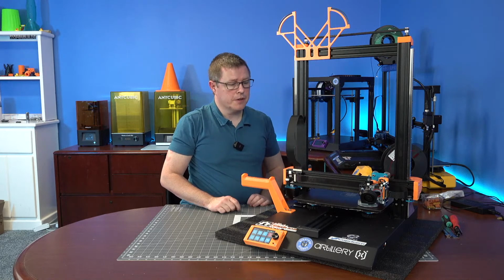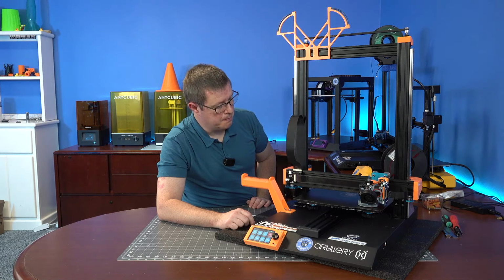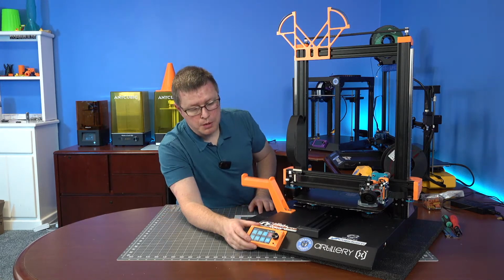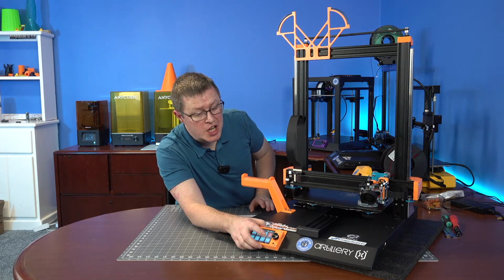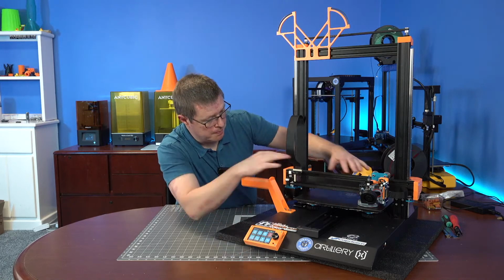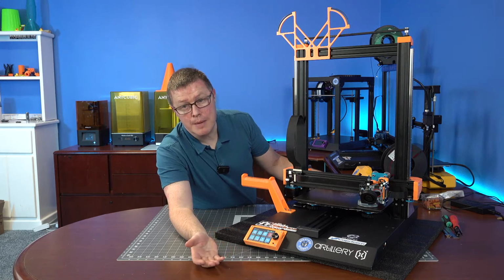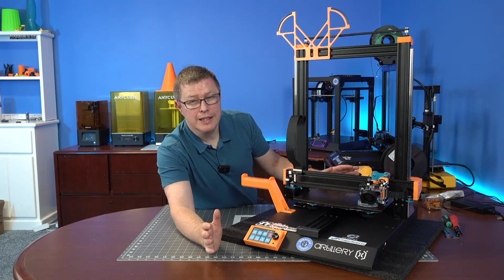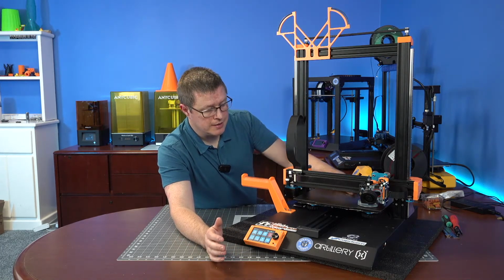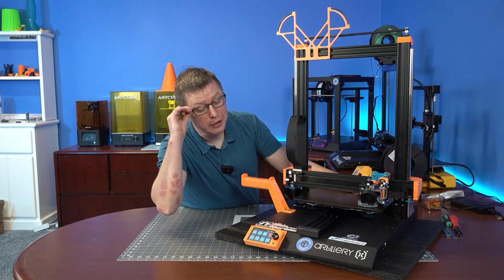So we're just going to use that for a quick and dirty corner level. It's not perfect. It's nowhere near perfect, but it's close-ish. And that gives it an opportunity to really test the actual mesh surface mapping. People call it mesh leveling or auto bed leveling, but that's kind of a misnomer. In CNC terms, which is what these are, little CNC machines, it's called surface mapping.